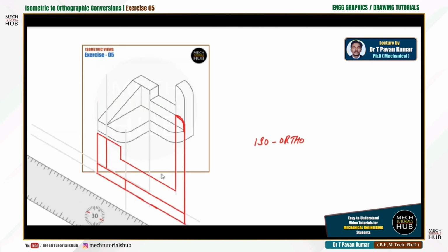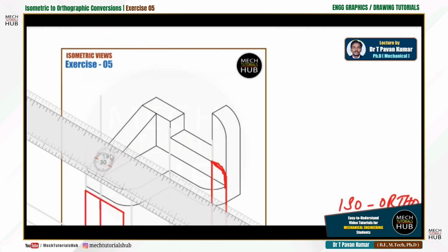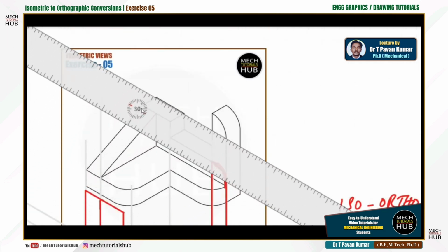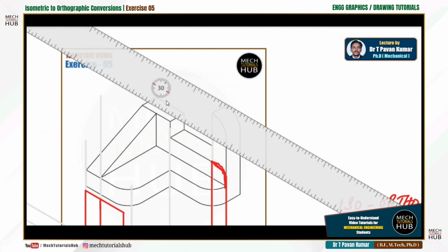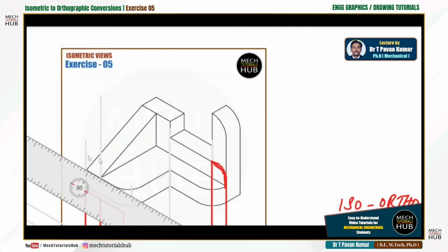So, front view. When it comes to the top, the complete picture will change. Now with the same scale, if I use 30 scale here, when I view from the top, what exactly is visible is, if I consider from the top, this edge, the complete edge, is visible. That means this box is visible, followed by this box, followed by this, which looks like a box again from the top, not like a fillet cross section.